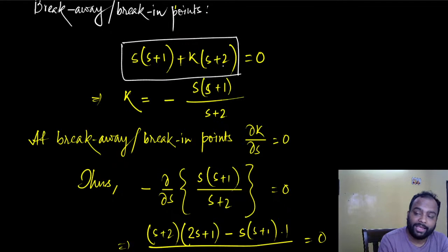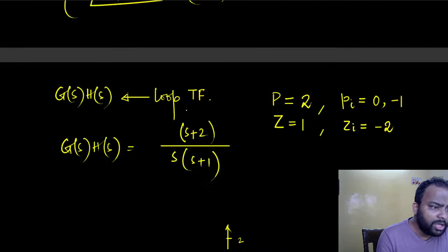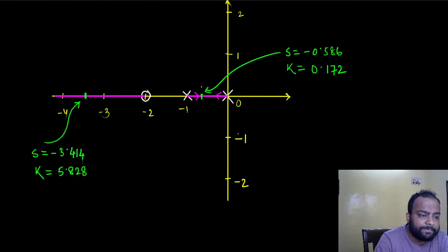And not only that, you won't even be able to force an instability on this. The system will always be stable as long as k is positive, and of course k is positive. So make sure to verify that using the Routh table. So if you apply rule number 4, you will see that the system can never be unstable, and also you can never force a row of zeros situation. Just verify that yourself. With that verification, you would see that of course the poles cannot go to the other side. So they have literally nowhere to go.